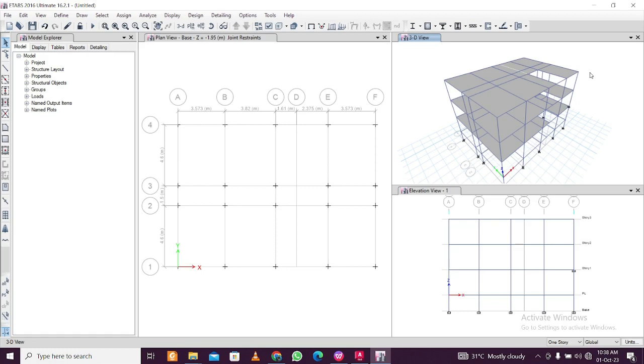And when we are not designing the staircase here, we are only doing it for the load. So it's better if you just consider the load of the staircase, in my view. You can try making a video on the creation of the staircase also, but in this video we'll create a landing beam and assign the loads of the staircase on the landing beam as well as the roof beam above it, and we'll also tell you the procedure.